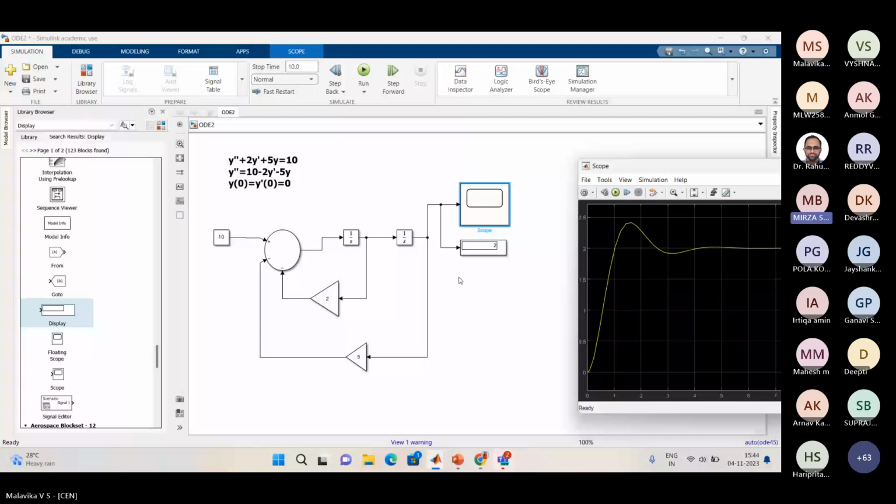For which we have to connect a scope directly to the first? Yes. Or we can take two inputs in the scope. That's the way you should debug every circuit. So from the input, it is fine. Then next stage, that is fine. Then check for the final output. Yes, now I'm getting it, sir. Some issue with the lab. Okay. Thank you.